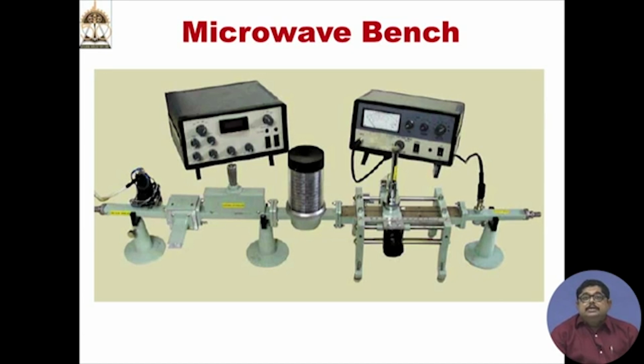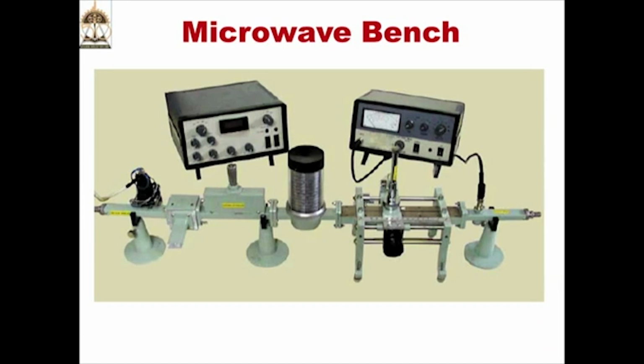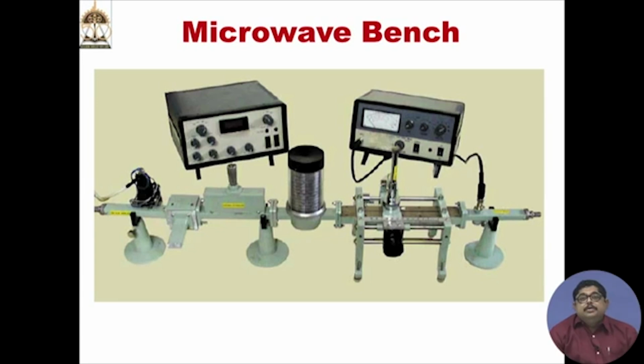Then you can see there is a cylindrical thing that is called a cylindrical microwave cavity. It is a frequency meter, also called a reaction type wavemeter. There are some graduations on the cylindrical body, and that is where the frequencies are read. This is the mechanical way of reading the frequency, but then we pass that to a waveguide section, a rectangular waveguide, which is a basic transport mechanism in high frequency, particularly in the gigahertz range, and if you have sizable power, waveguide is the mode, not a coaxial transmission line. So, in microwave, generally the fundamental transport mechanism is through waveguide.